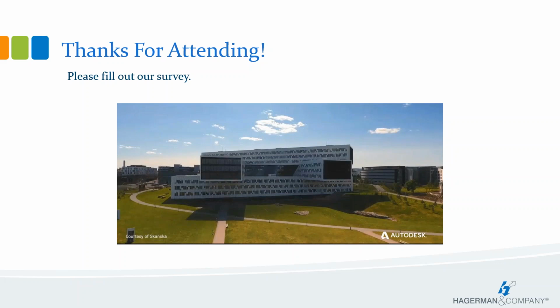Now, there is another feature for drawings that I didn't show you during the demo portion, and that is camera views. So if you have objects that cross from one level to the next, and you want to make sure it's shown correctly on your drawings, you can create a camera view. And that camera has a box associated with it for clipping purposes, and you can make that box whatever size you need and use a camera view instead of one of the other drawing styles that I use, like the typical plan view, which only shows you the plan and a little bit above and a little bit below. So take a look at camera views for that sort of thing.